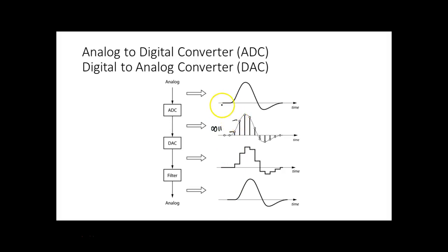And then up here, it might be this number right here, right? You understand? And then that would be the peak, which might be that number right there. And then it would start dropping down. Okay. So what your PLC, or your computer, gets is a binary number. But how accurate it is would depend on how many digits you have in your binary number.